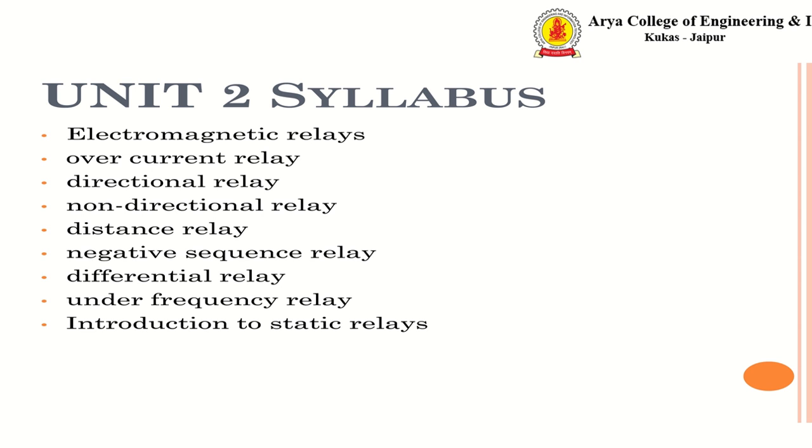Similarly, distance relays are also there. This type of relay works on identifying parameters. Since we use these types of relays for a particular area, the parameters are already fed into the network. They are already set in the brain of that relay, and when the CT and PT provide input to these relays, it is compared to the set threshold value.